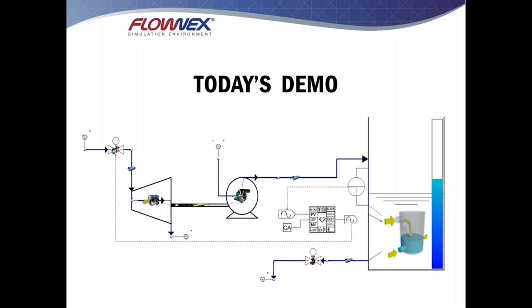So there's quite a large delay inside of this side of the system. Adjusting the valve position is going to ultimately adjust the flow rate of steam through that pipeline, which will change the power into the shaft. This will either speed up or slow down the turbine pump arrangement. Then that pump will either increase or decrease its flow rate into the tank, and that will ultimately affect the level inside of the tank. So there are multiple layers to this control network.